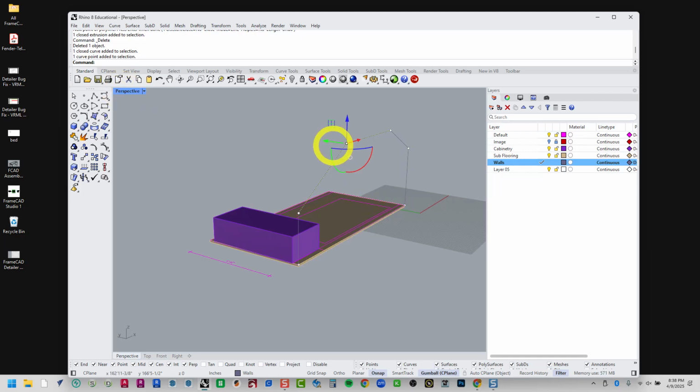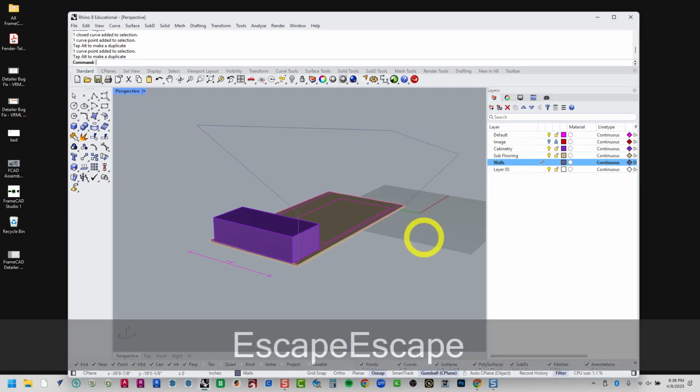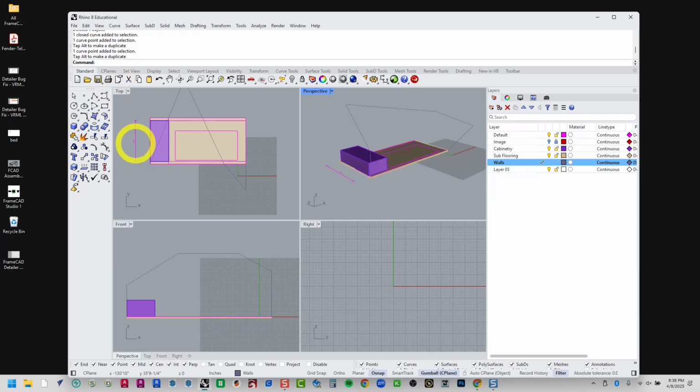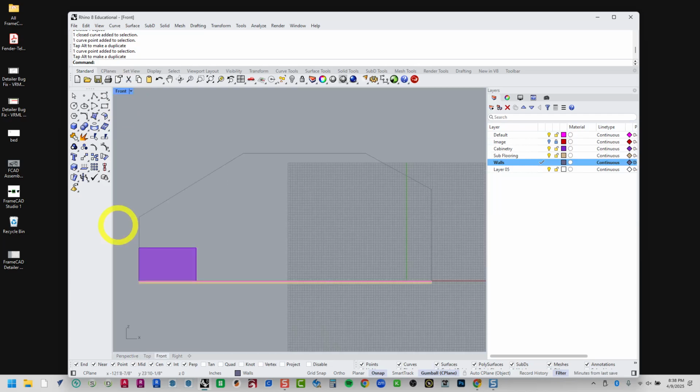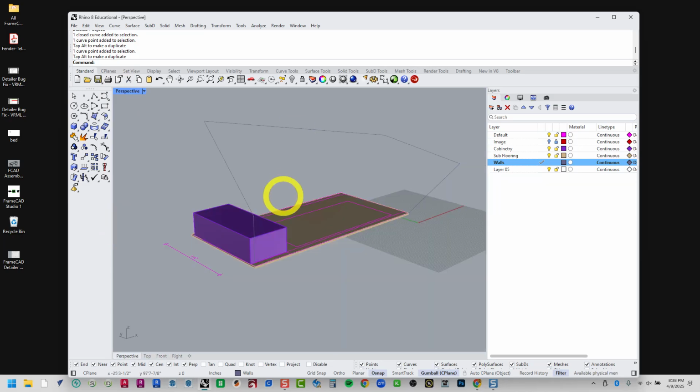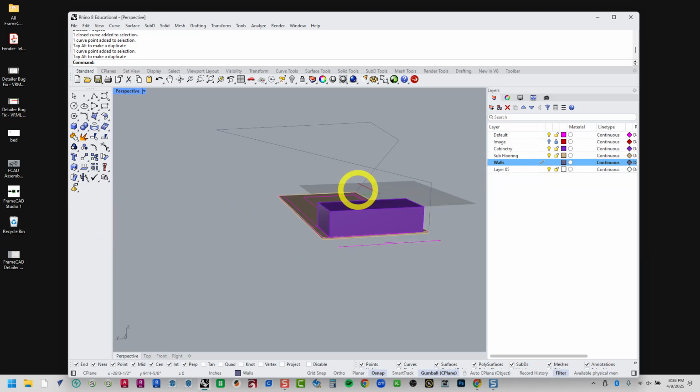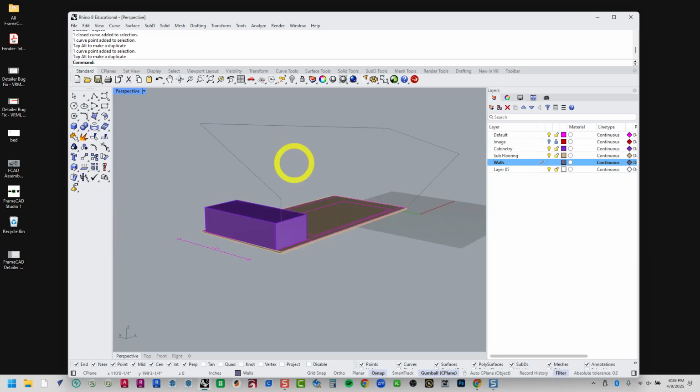And if you're not actually snapping to anything and you're in the front view, if I just drew a line here in this front viewport, right, let's make a nice funny curvy line. If I draw a funny curvy line like this here in this viewport, go back to my perspective view, you can see where that line is drawn. It's drawn where the x-axis is equal to 0, or y-axis is equal to 0. Yeah, it's where the x-axis is, right? So notice the difference of where all these points line up.